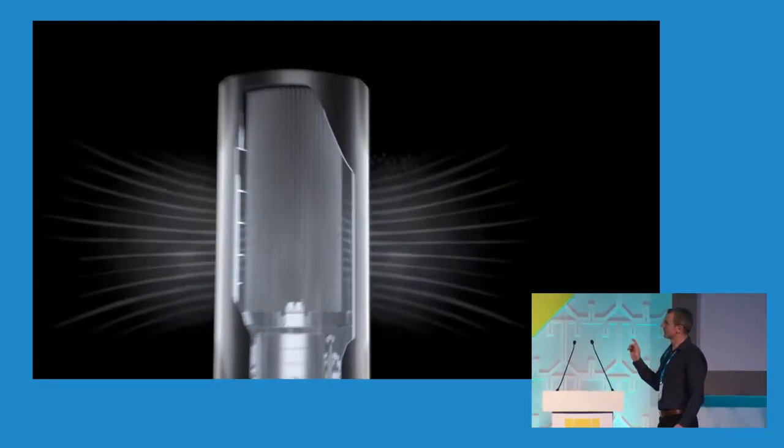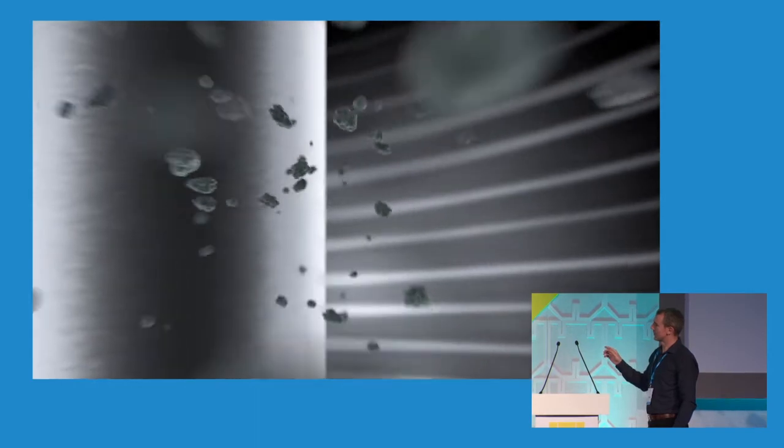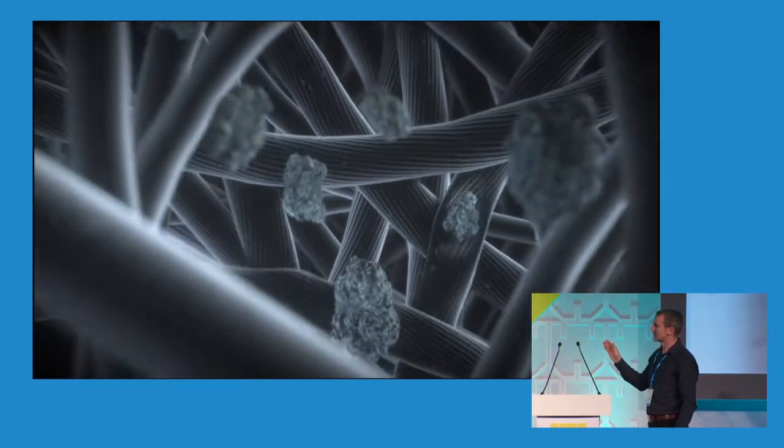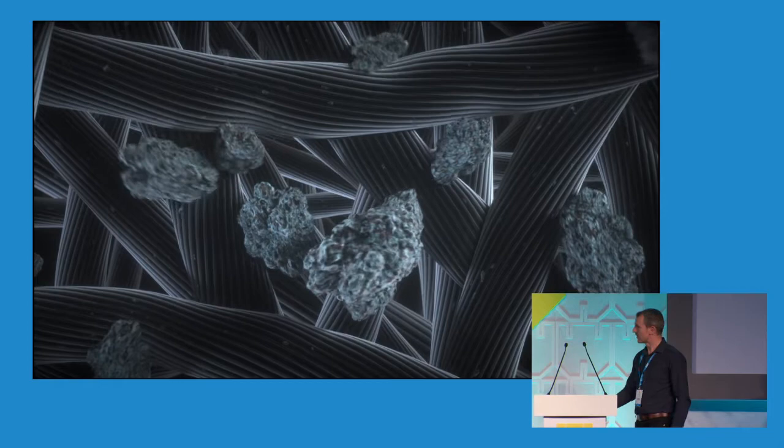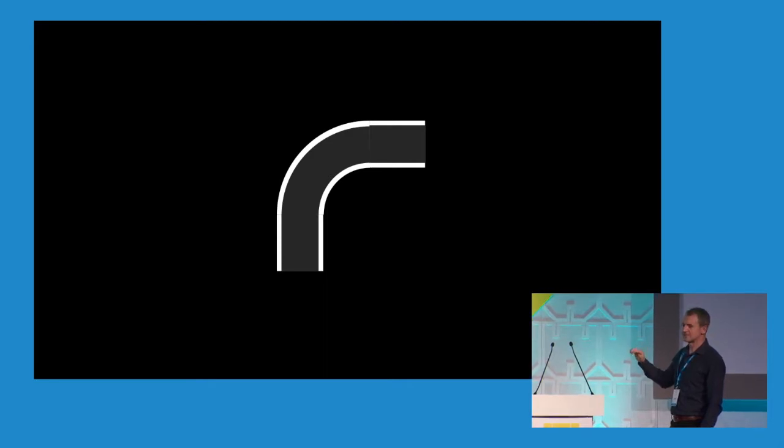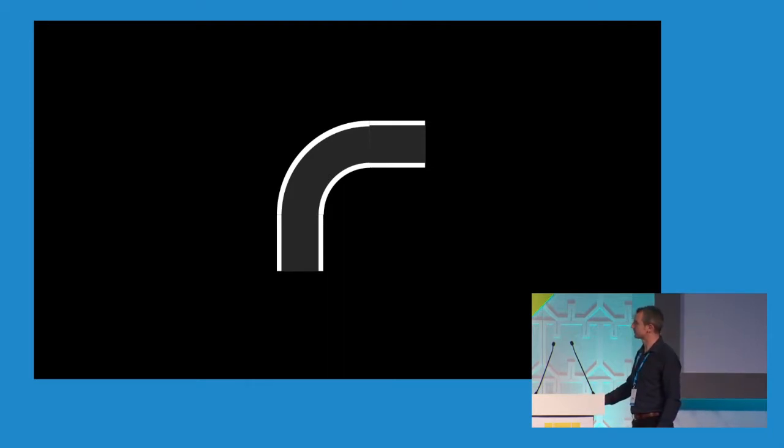So that's all well and good. We've seen that there are some tricks to play. We know that bigger pipes are better, but sooner or later, you kind of have to send that flow around a corner. Now, I'm sure you can imagine that that pipe is pretty much ideal. If you want to send that around a corner, you want a nice big radius, and actually, the bigger the radius, the better. But there's a point of diminishing returns, which is when you get to the point where your radius is about the same as the diameter of the pipe. Once you get beyond that, it's pretty subtle differences. So that's what we try and aim for.